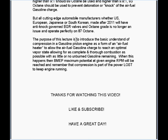The purpose of this lecture is to introduce the basic understanding of compression in a gasoline piston engine as a form of an air-fuel heater to allow the air-fuel gasoline charge to reach an optimal vapor state, allowing for as complete and thorough combustion as possible with as little or no unburnt gasoline remaining. When this happens, then the brake mean effective pressure maximum potential at given engine RPM will be reached. And remember that compression is part of the power loss to keep the engine running.